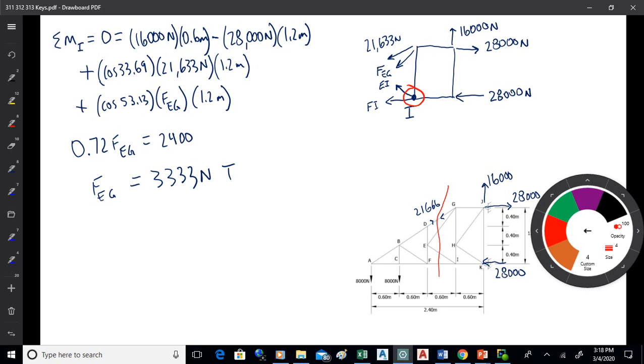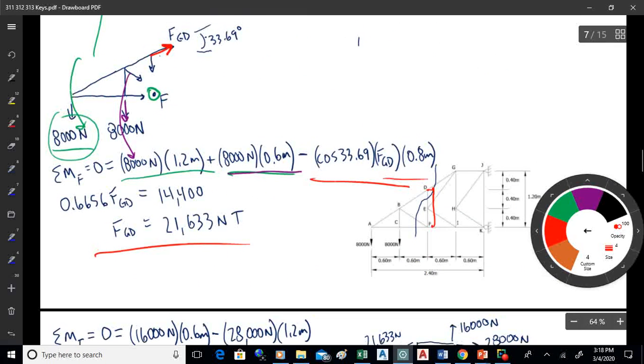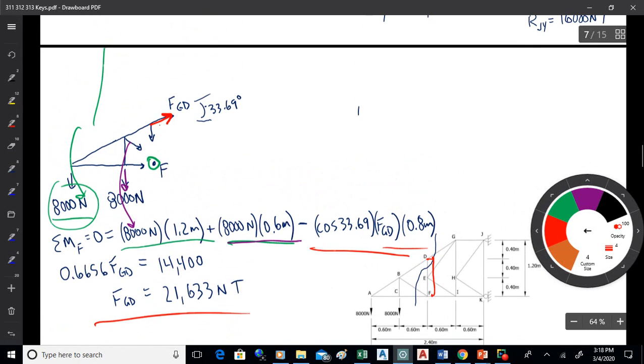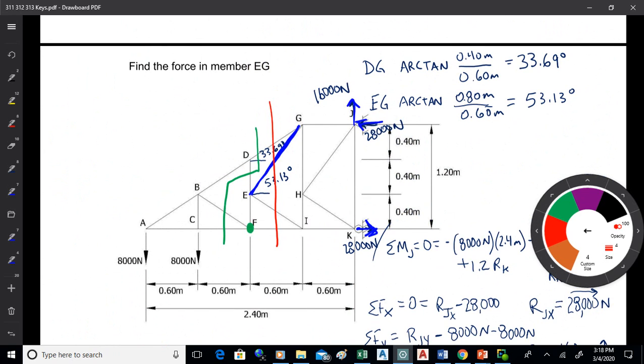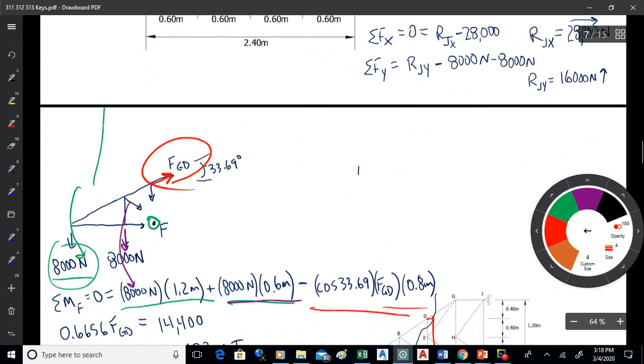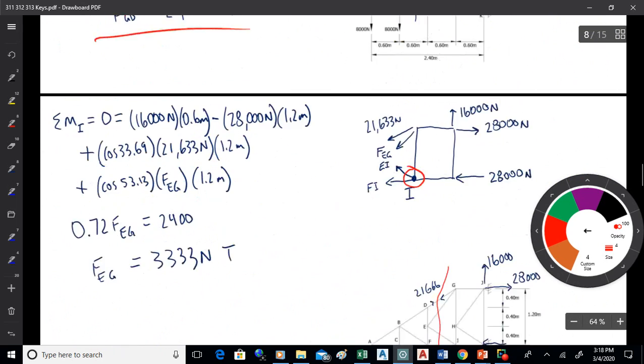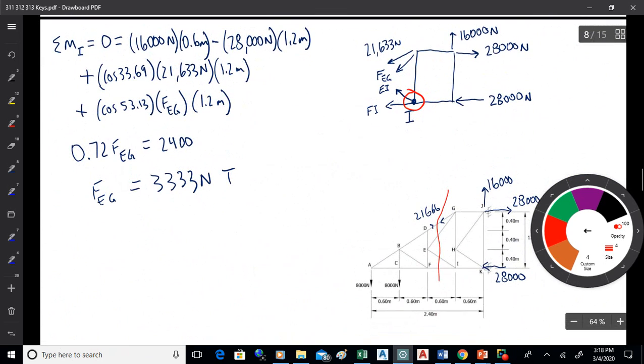Yes. So when we took the moments about F, we were solving for which number? When we took the moments about F, that was to get DG. Right, and then use that as one of your unknowns for your first cut. Right, because see, the problem was the first cut had 4 unknowns. I got to get one of them out of there. And so the whole purpose of doing that other step was to get DG. That was the one I could get. Now it's known. Now that original cut will work. That's the thinking on that. Okay.